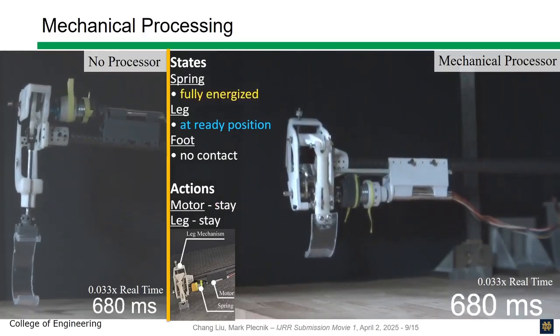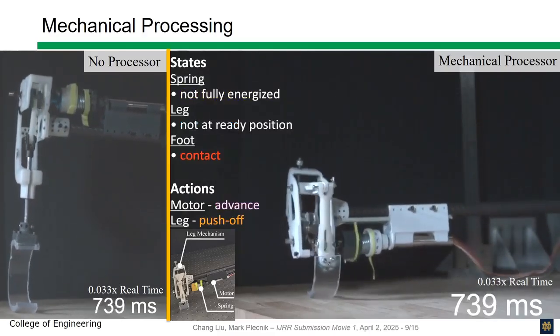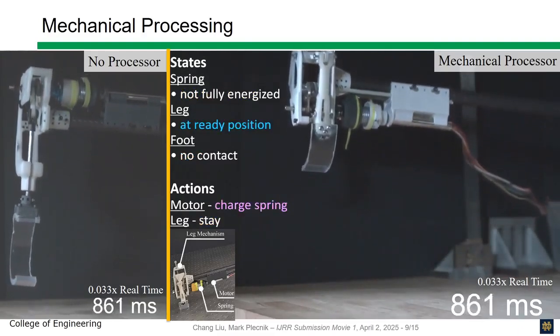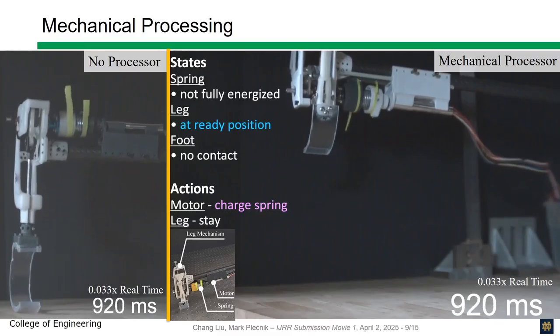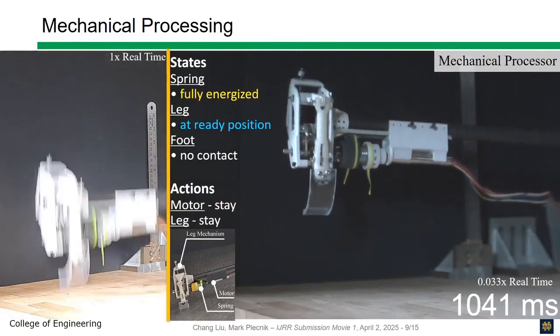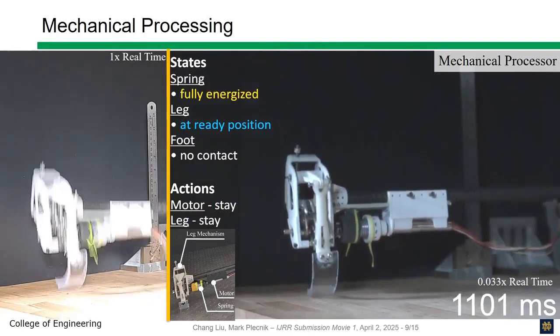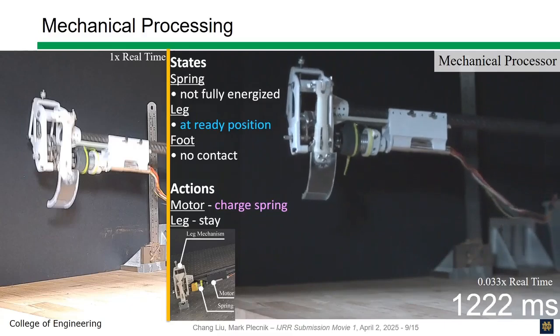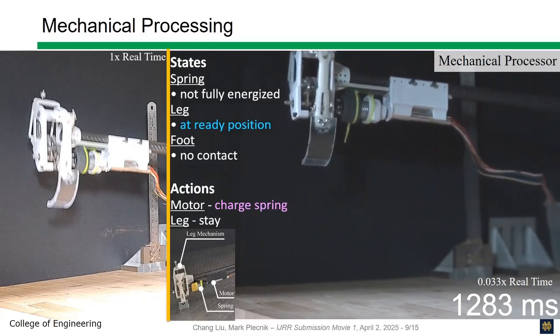With the series elastic actuator pushing against this singularity, the leg no longer advances, but instead the elastic element experiences large deflection, resulting in energy storage. Each hop cycle lasts 400 milliseconds, with only 40 milliseconds spent in contact. Auto-contact spring charging allows ample time for a small motor to add energy to the system.